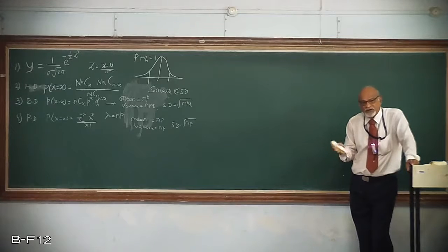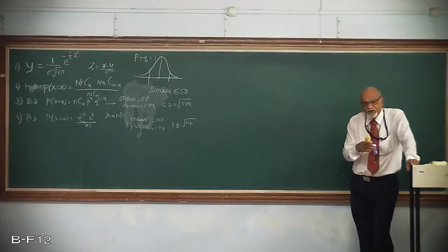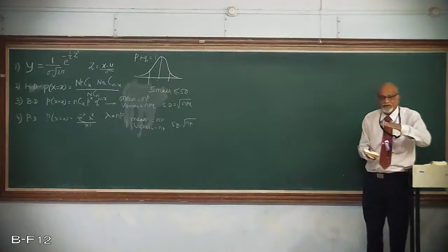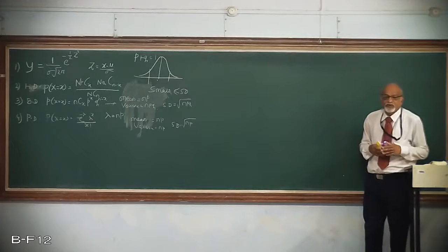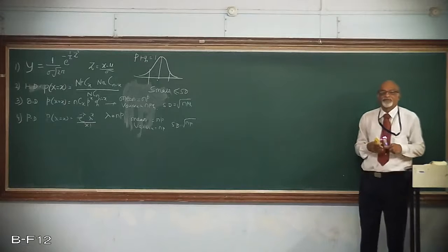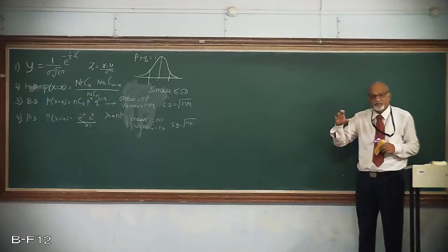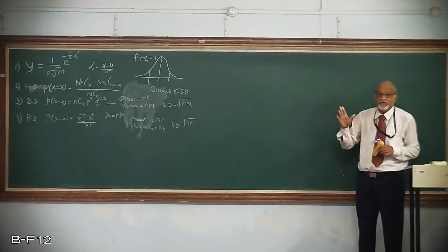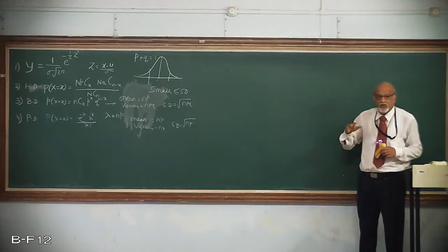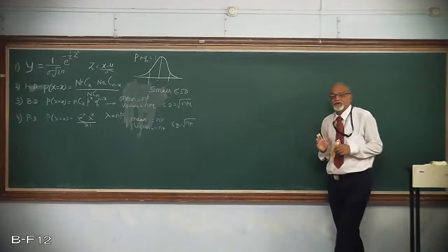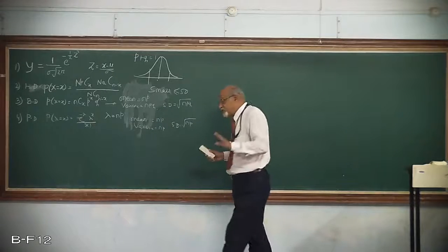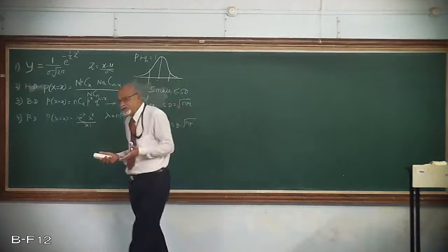What I will do, I will start the process. After manufacturing some 10 items, I will just see whether it is going as per the intended norms or whatever specifications I had set up. Then what should I do? I will take the sample and then try to compare. Is it going as per whatever I have planned, or is it going to deviate from this? That is what I will go on checking. Okay? That is what exactly is being done in practice.